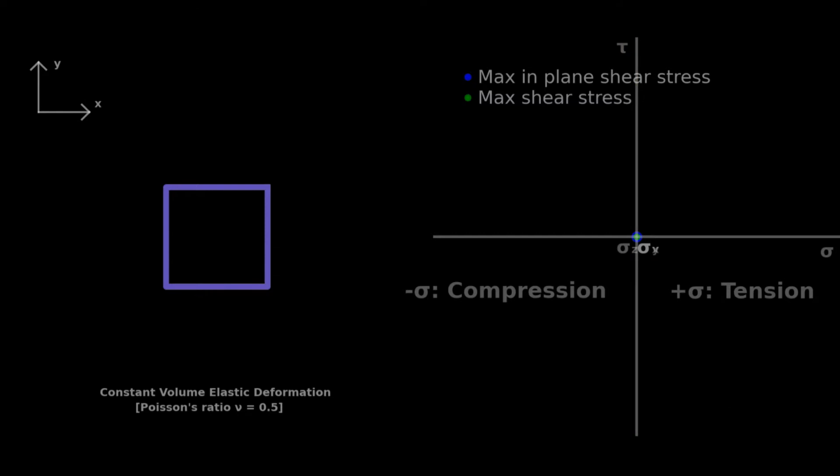A principal stress is a stress which only has a normal component and no shear component. As a result, the principal stresses always lie on the x-axis of the graph. The red points on the graph will be principal stresses. The Mohr circle is formed by drawing a circle between the points representing the stress applied to each axis.